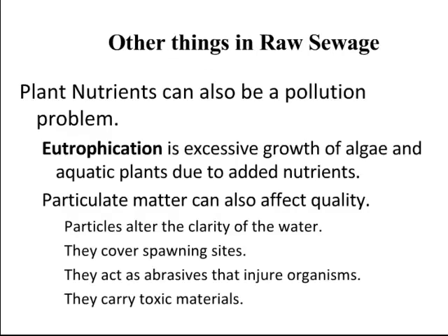And sewage and bath and washing machine runoff also contains plant nutrients. Now these plant nutrients, nitrogen and phosphorus, are what is also found in fertilizer. So if we add these nutrients to the water, we are fertilizing the water. Now that may seem strange to be listed as a problem. Some people would think, well, having fertilizer added must be a good thing. The problem is if we add too much fertilizer.